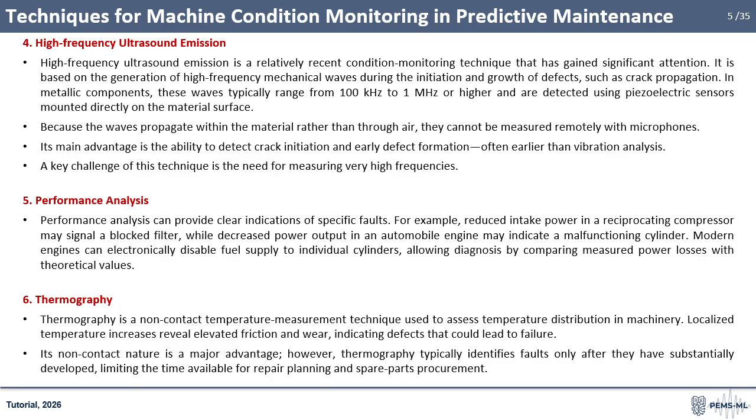Thermography is a non-contact technique used to measure temperature distribution in machinery. Localized temperature increases reveal elevated friction and wear, which may indicate developing defects. Its main advantage is non-contact measurement, but it typically detects faults only at later stages, reducing the time available for maintenance planning.